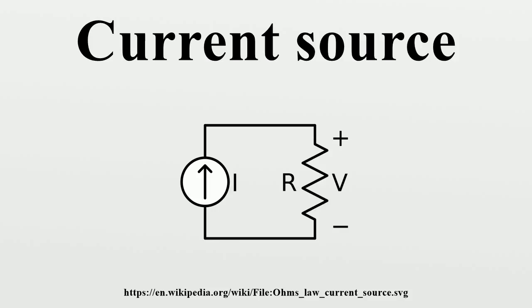For a nearly ideal current source, the value of the resistor should be very large, but this implies that, for a specified current, the voltage source must be very large. Thus, efficiency is low and it is usually impractical to construct a good current source this way. Nonetheless, it is often the case that such a circuit will provide adequate performance when the specified current and load resistance are small. For example, a 5V voltage source in series with a 4.7 kΩ resistor will provide an approximately constant current of 1 mA to a load resistance in the range of 50 to 450 ohm.